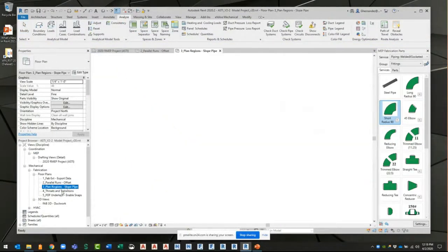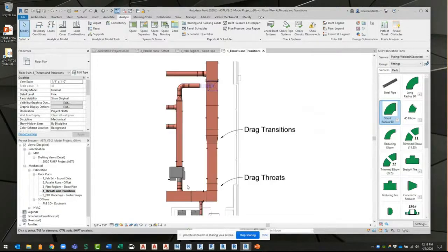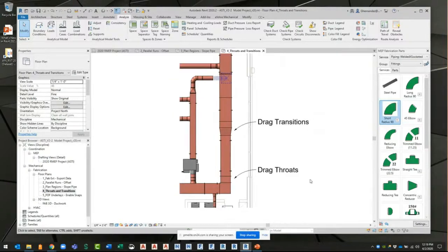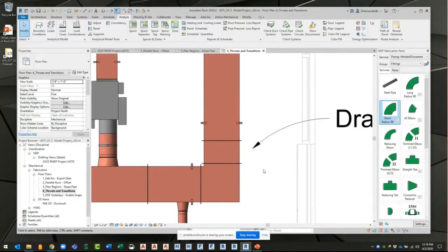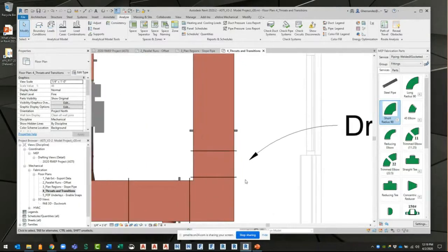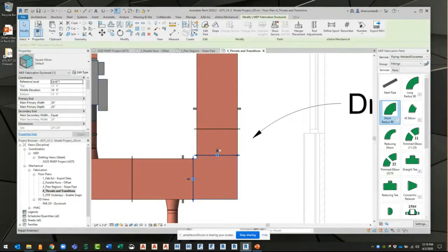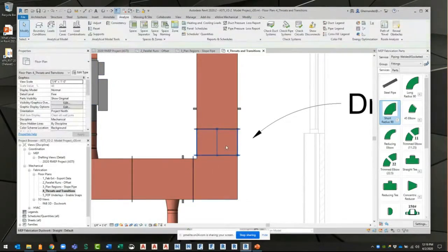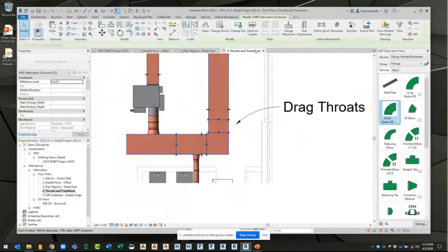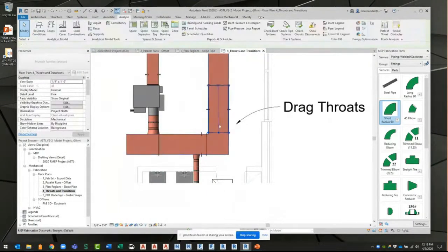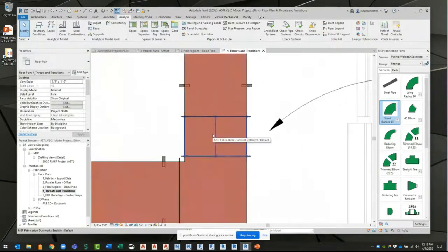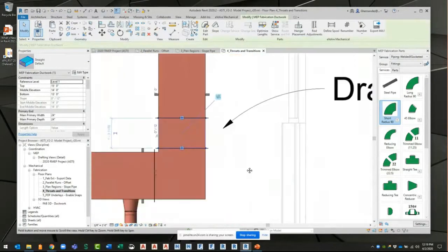Now, before I get into my slope pipe, I'll do the pipe at the end here. Let me show you this trick that I learned. This is from a fellow instructor. So with Revit families, you cannot drag the throats of a squared elbow like this, right? And when I use the optimize links command, I get weird breaks, right? I'll undo that. I needed that break there. But sometimes you get weird breaks like this where it's split up, okay?